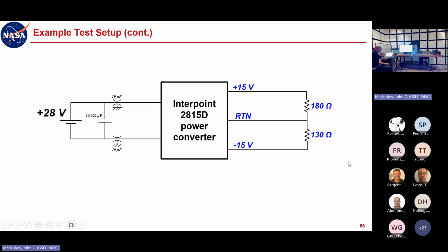Yeah, there's no connection to the ground plane here. I mean, okay, we EMI people, we know there's no such thing as an open circuit. There's capacitance, right? But there's no conductive connection here. So it is, for all practical purposes, a transmission line with an open circuit termination here. So it's going to have different behavior. It's still a mismatched transmission line, but now it's with an open termination instead of a short. So you've got to alter your expectations based on that.